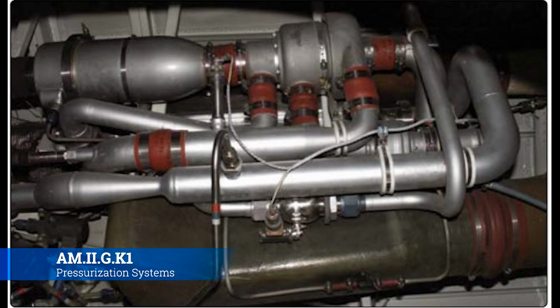Now your jets, your Hawker, your Challenger, and so on, all the way up to your Boeing and Airbus aircraft, are going to use their air cycle system or vapor cycle system to pressurize the aircraft. They're not going to have an outside air compressor just to pressurize the cabin, because they also have an environmental system to control the temperature and all other good stuff. We're going to get to that in just a minute, but that's how you do jet aircraft.